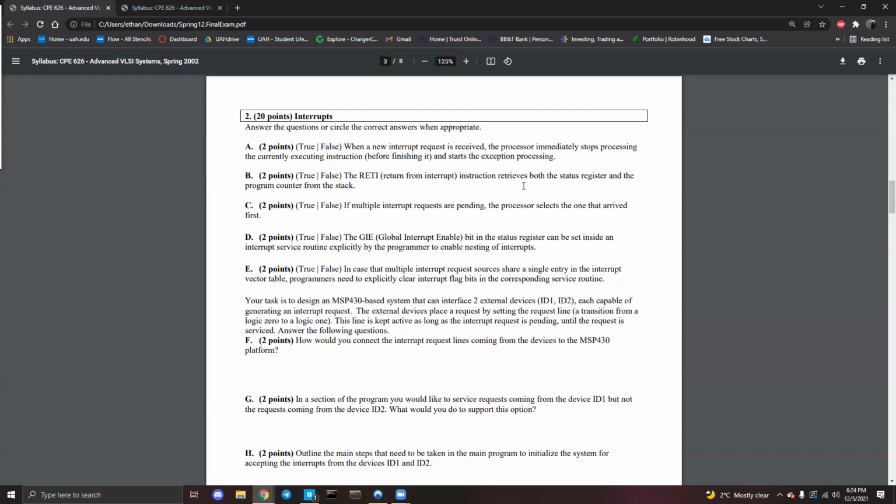So what this really means is, let's say you have an interrupt that could be activated either from a switch being pressed or pressing Q on your keyboard. And you go in, and what happens is either of those flags could be set. It's just that the hardware sees the interrupt, so it goes into your routine. But within your routine, since it's multi-source, you still have to figure out where it actually came from to process it properly. And because of that, you also have to reset the corresponding bit to the next nested routine that you make. So when you enter an interrupt, it's always a good idea to clear the bit. I don't think we ended up entering over something and had to do it again in one of our labs.